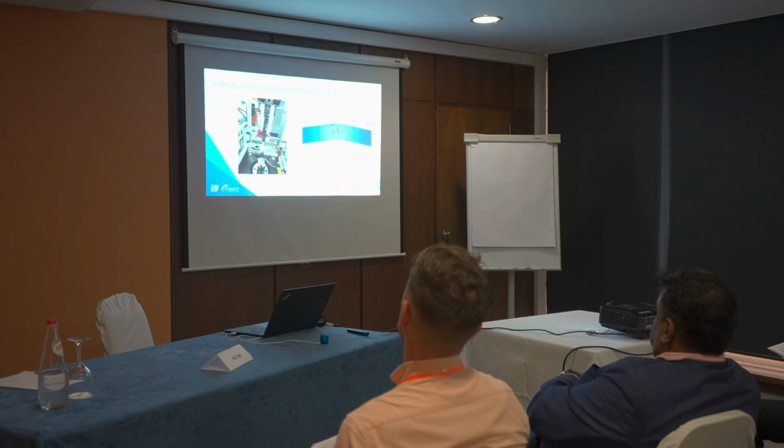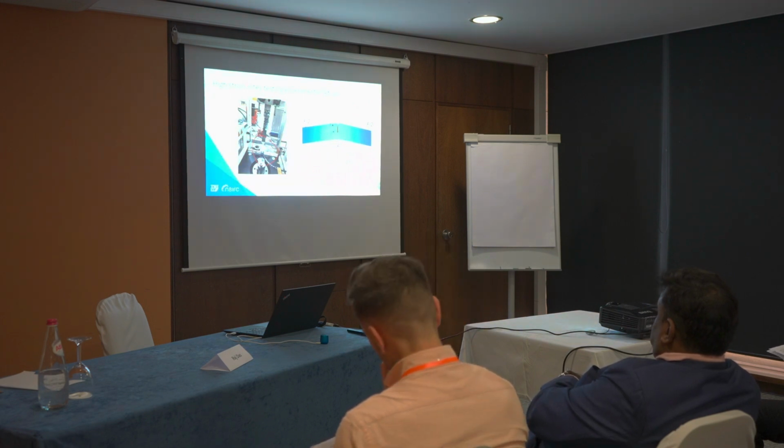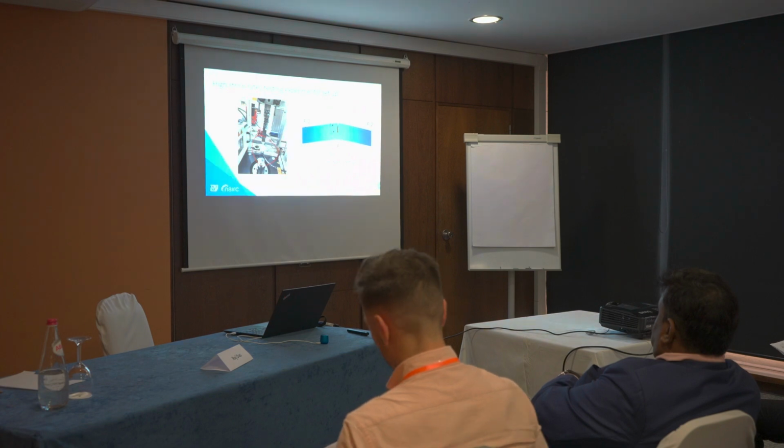This is used to be able to utilize the camera, and it's captured for the digital image correlation analysis. We also have the 3-point bend specimen here, which we use for the impact testing. These are used in order to obtain numerical properties at high strain rates, such as fracture toughness and the ultimate tensile stress.